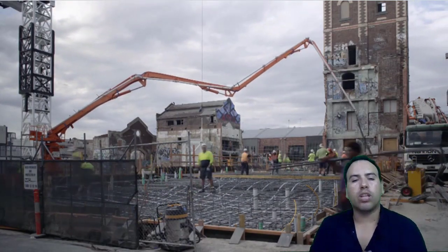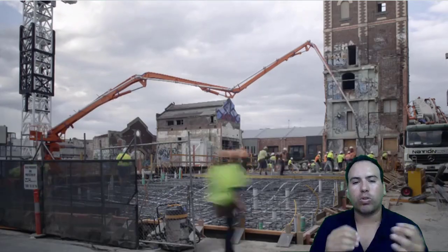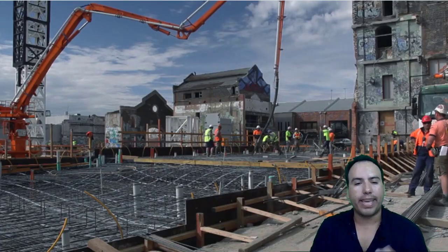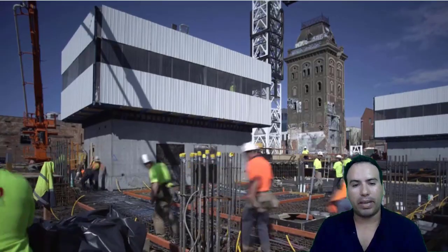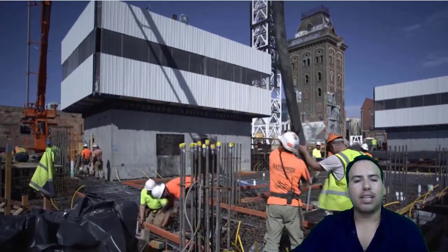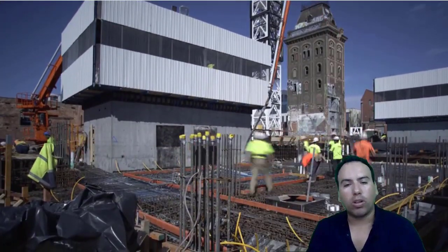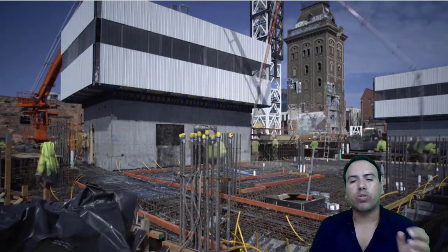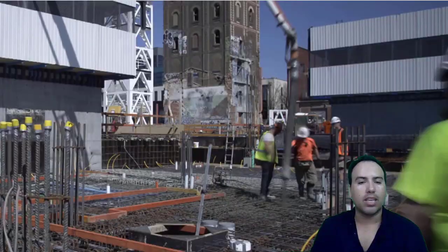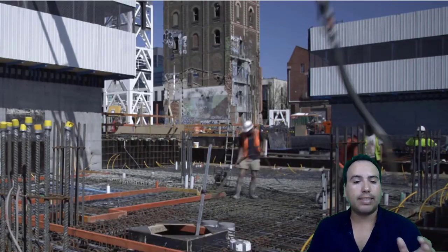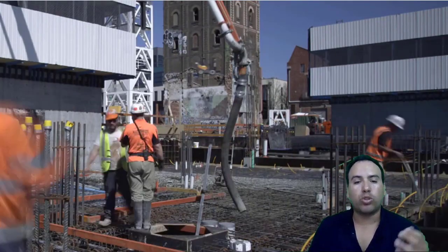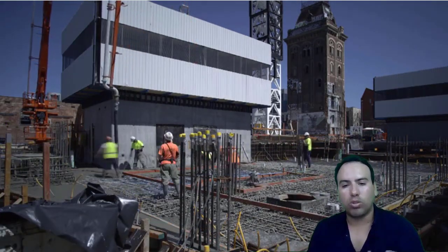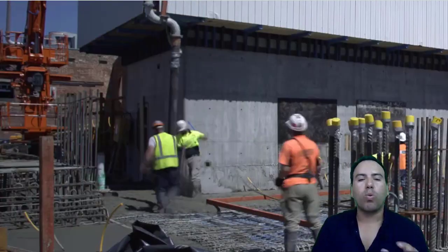And the forces transfer from the slab to beams either in one way or in two ways. The total system completely depends on the geometrical dimensions of the slabs. Slabs might be supported by columns only, in which case two-way action will prevail. If the ratio of long side to short side is less than 2, it is considered a two-way slab, and if the longer side to shorter side ratio is greater than 2, then it is considered a one-way slab.